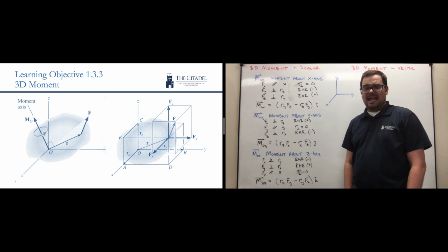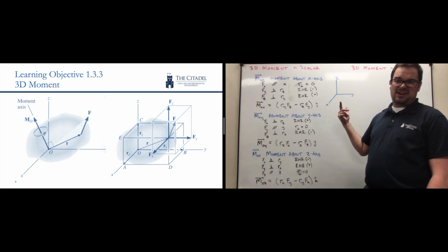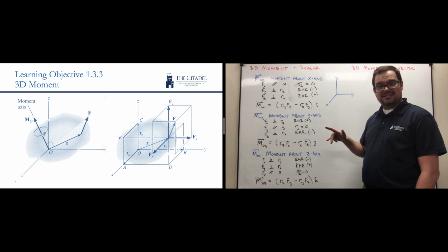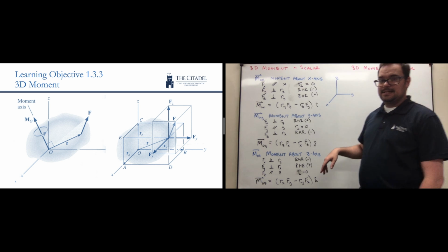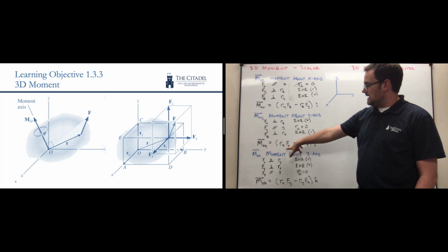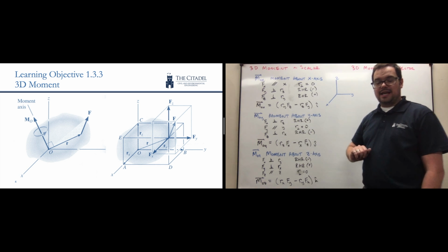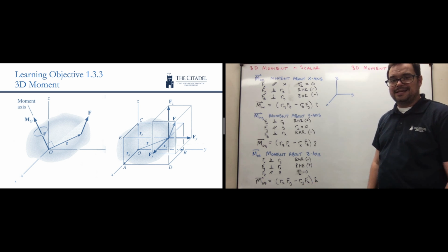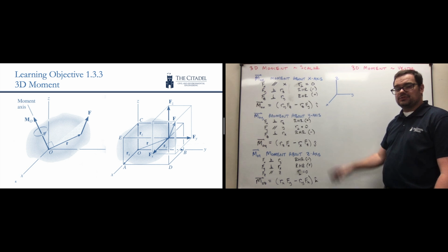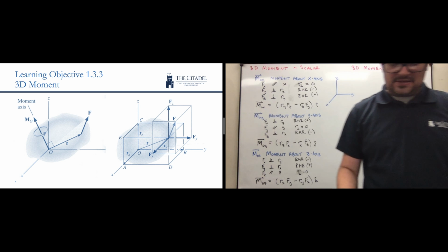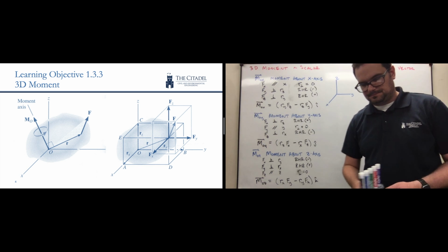That's fine. And in 2D, really, this isn't bad at all because we know that in 2D, our forces are only in the X and Y direction. So the Fz component goes to 0, and the Rz component goes to 0. So this goes to 0, and this goes to 0. So we only have our k component. So often we'll use our right-hand rule and our scalar notation to calculate moment in 2D. But in 3D, it's a lot nastier. So sometimes we do it this way, pulling data directly from our FE reference handbook, looking at moments or couples.